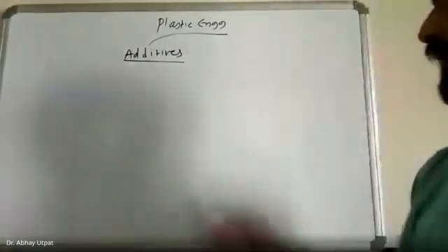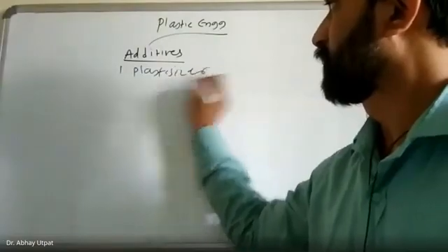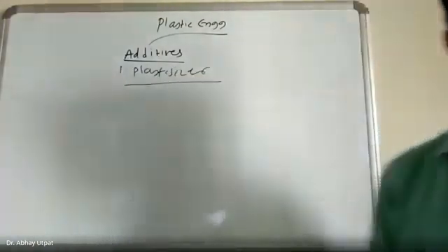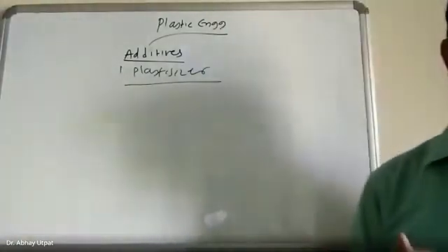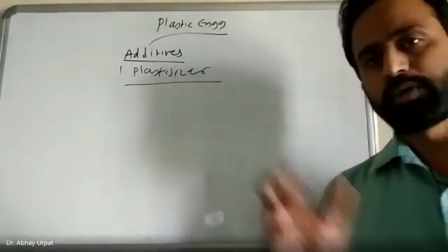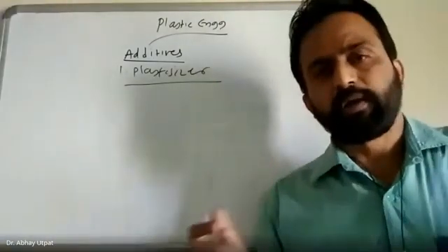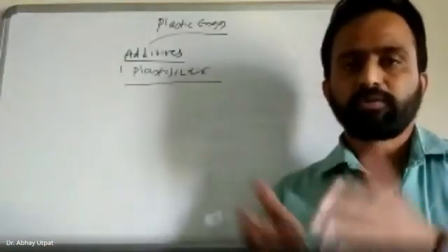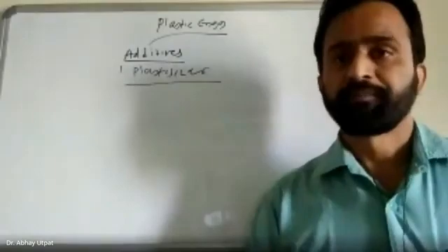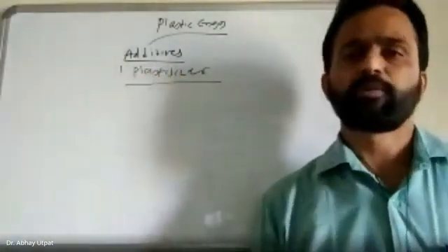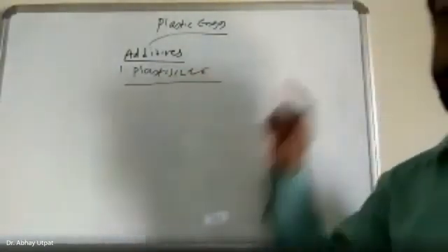One by one you write down plasticizer. So plasticizer is an element which is added to improve the flow characteristics. These are added for improving the flowability of plastic. So if you have one plastic element which may be costlier, some other element like plasticizer is added. So the flowing characteristics your original plastic has will be improved like anything. That's why these plasticizers are some kind of resins which are added for improvement of flowing characteristics. In short, you can write for improving flow characteristics.